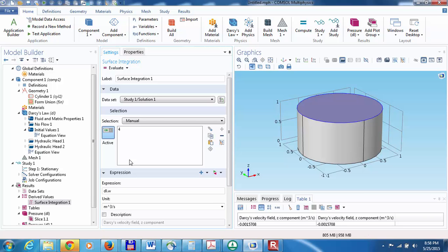So you cannot be guaranteed that the Darcy flux calculation is going to give you boundary fluxes that will yield true conservation of mass. That is, rate of change of storage is equal to the net flux through the boundaries.